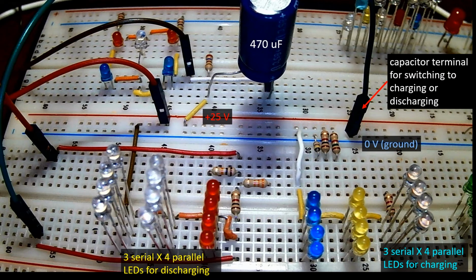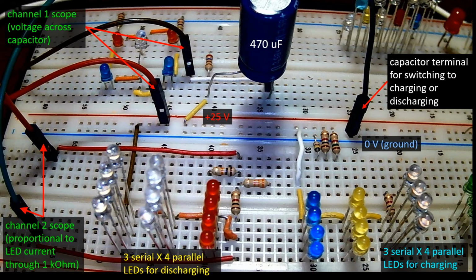Most relevant for your work of this step A1 is the setup for measurements that you should take note in order to describe, explain, and discuss for your report of A1. There are 2 quantities. The voltage across the capacitor as a function of time, which is measured by the Digilent AD2 scope channel 1. And the current that is indirectly measured via Ohm's law as the voltage across a 1 kilo ohm resistor, measured with scope channel 2. Various aspects of the circuit will be clearer in the series of demonstrations that follow.